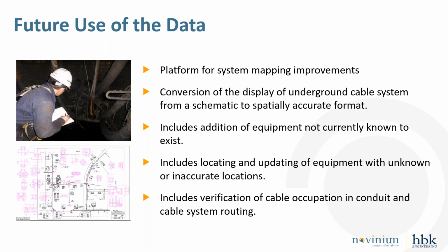The other important outcome from the design user standpoint was that we were not only creating the spatially correct depiction, but as a result of the data being collected, we were able to accurately depict the position of a cable circuit within the cross-section of a duct bank. Prior to this, design users might perform a new design expansion to tie into a circuit that actually existed in a duct bank and manhole system on the other side of the street, instead of in the location depicted in the GIS mapping system.